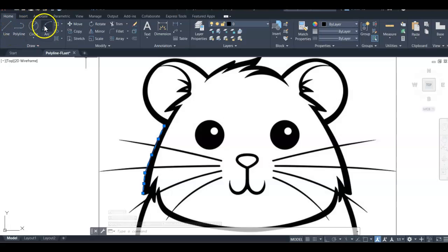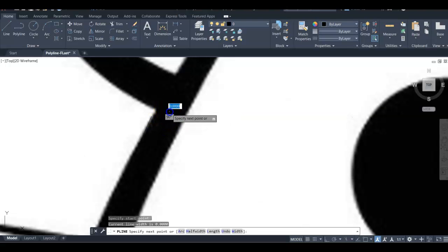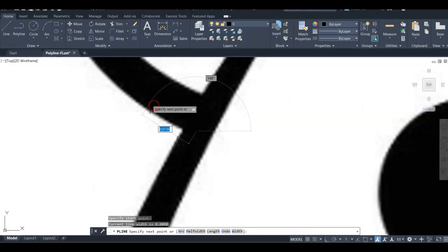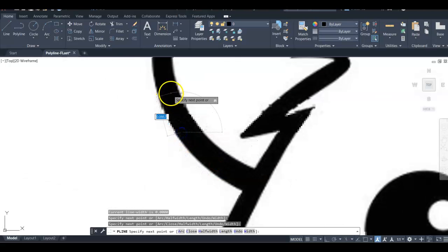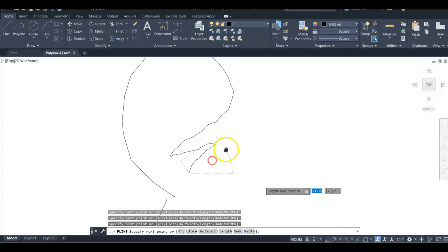All right, now I'm going to continue on with the polyline, and we can come right on back and pick these polylines and just keep clicking. So on your curves, when we're looking at these radii or these circles, the more nodes you click, the better off you're going to be. So it doesn't even hurt just to sit there and do some clicks like this to more or less get all of that. Now I'm just rapid clicking, so be careful. You want to see what it does.